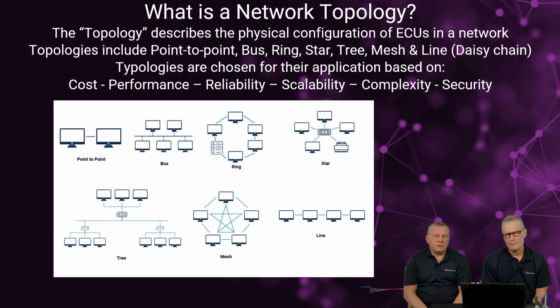The key thing to understand is when you're doing a network diagnosis, you need to do some form of just-in-time learning on the system that you're looking at. Because if you don't understand how the network is configured, that's basically what topology is: how is this organized, how are the modules or nodes connected on that bus? Unless you know that, you could make fundamental mistakes in your diagnosis. So although you can dive in and start taking measurements if you have a fault on that particular network, understanding the topology matters.